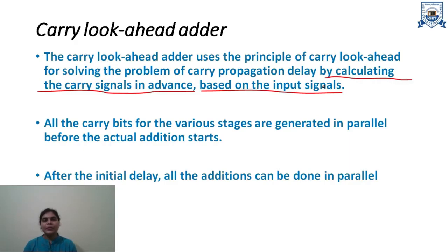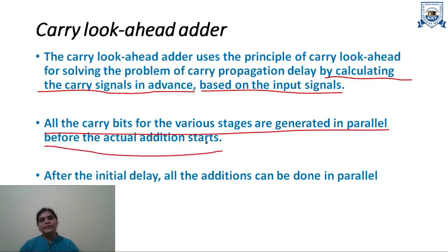So it will reduce the carry propagation delay. All the carry bits for the previous stages are generated in parallel before the actual addition starts. After the initial delay, all the additions can be done in parallel. Once it gets all the carry signals, the addition can be performed in parallel.